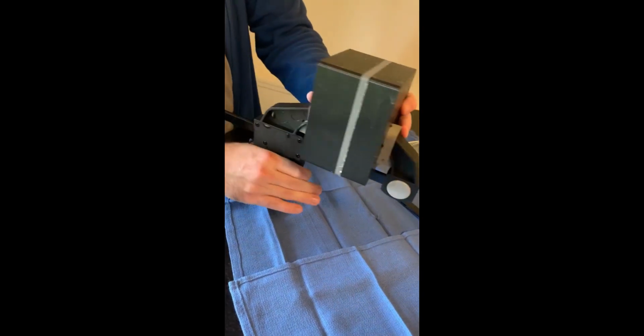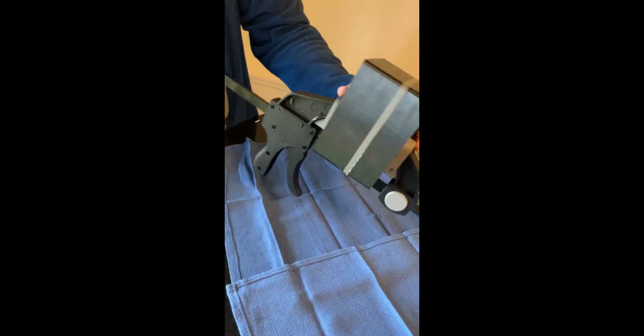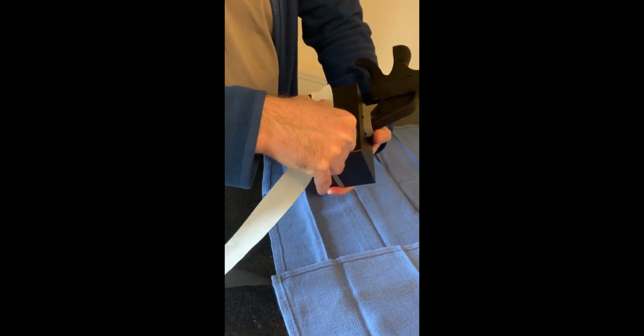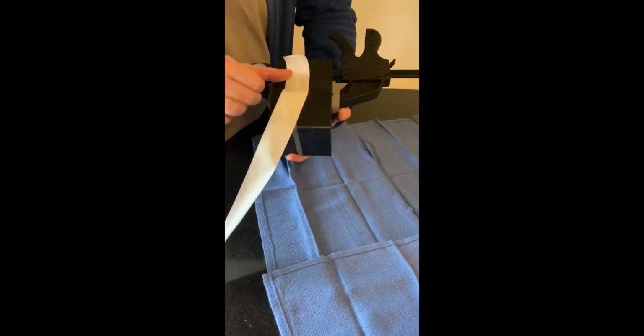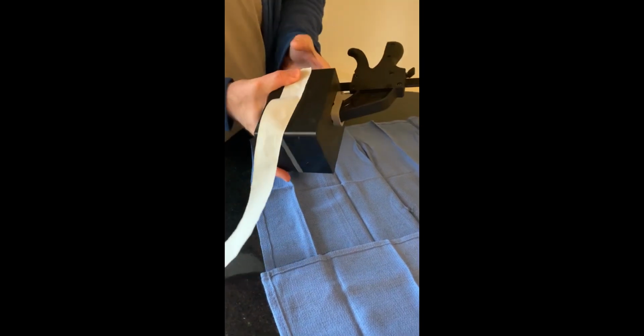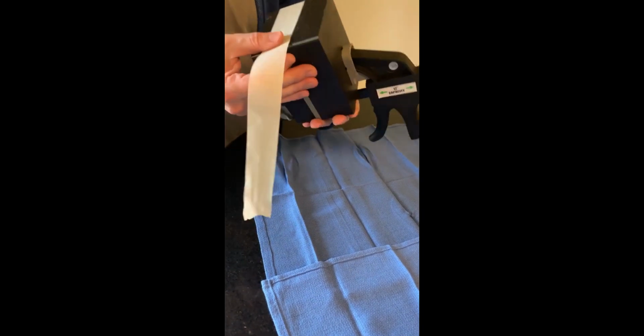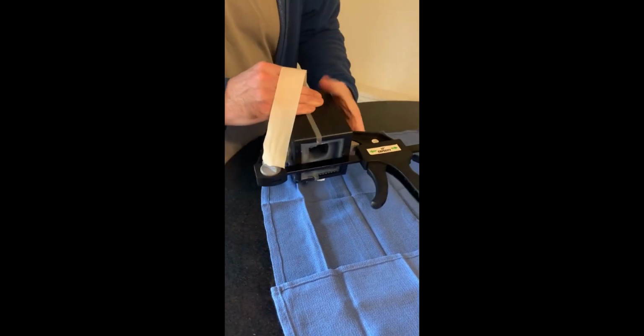Before the pour, you want to clamp the mold halves together. Now, if you have a really low viscosity resin, you might have a little leakage around the sides, particularly if the cure time is really long. So if you're worried about that, in addition to clamping, you can put some tape around the parting line to keep it from leaking. And then I actually will also put it into a plastic tray like this, so if it does leak, you don't get it all over your table.